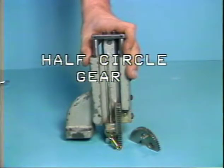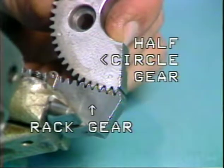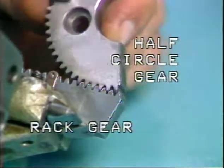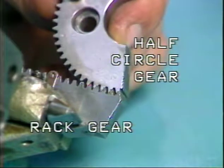This is the half-circle gear. The purpose of the half-circle gear is to transfer the movement of the straight rack gear to the friction clutch. The circle gear and rack gear mesh. Proper alignment during installation is important.